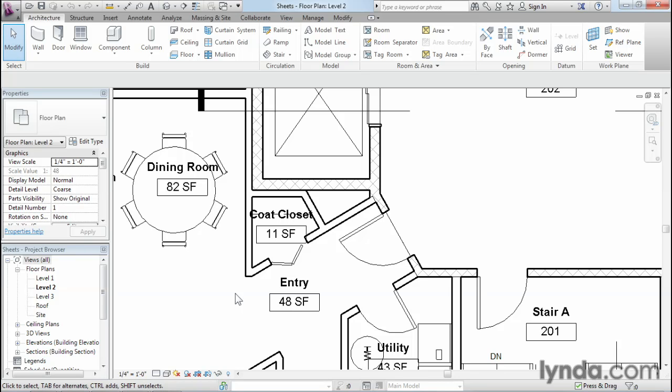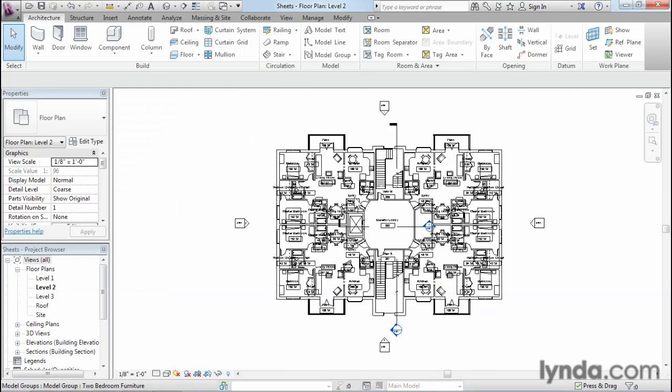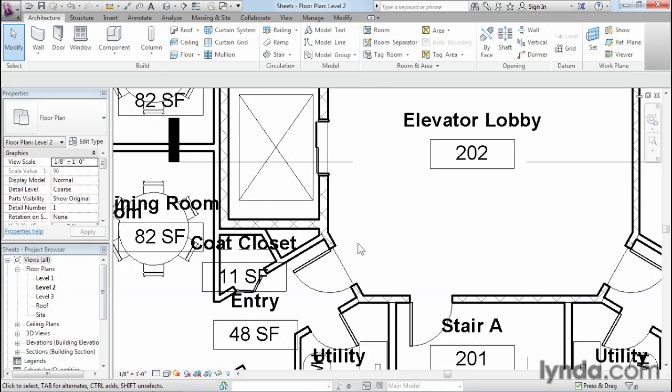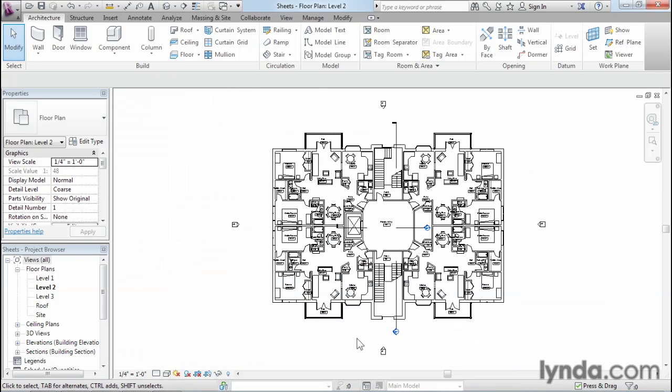The important thing that I want you to see is that the line weight display is built in, and it's tied to the scale. So if I came over here and I changed the scale of the drawing, so let's say I'm in 1/4 inch right now, let's say I change it to 1/8 inch, and then we zoom in again, you're going to see that that has an impact on not only the size of the annotation and other elements on the screen, but it does have an impact on the line weights as well. I personally think it looked a little bit better at 1/4 inch, and I'm going to set it back to that scale right now. So that's the first aspect of printing, is that basically that takes care of itself. No more plot styles, no more color mapping tables. What you see on screen is what you get in print.